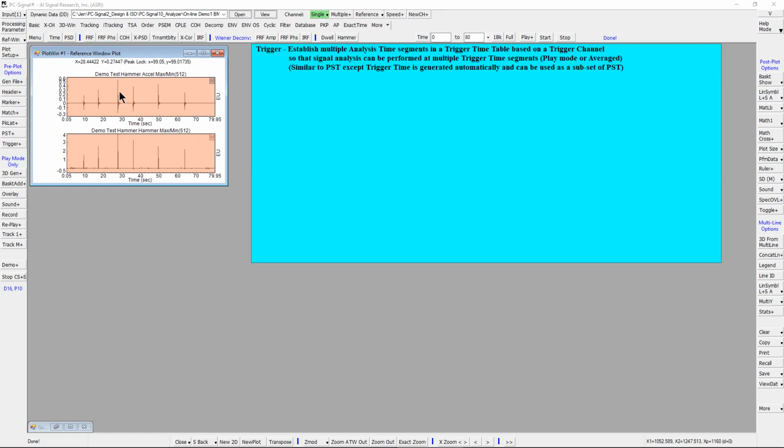The frequency response function, or FRF, between two structure locations can be computed from a hammer excitation and a vibration response measurement. Multiple hammering at the same location are usually conducted so that averaging can be performed to minimize statistical variance. In this case, Trigger provides a convenient feature for its signal processing.